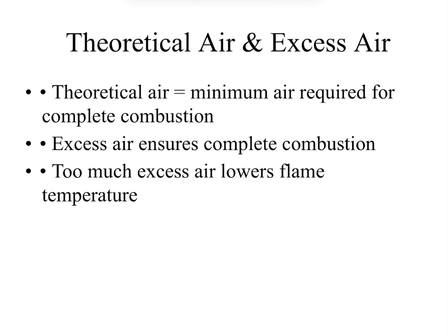And then we will move to theoretical air and excess air. Theoretical air is the minimum amount needed for complete combustion. In practice, extra air is usually supplied to ensure all fuel burns completely. However, excessive air can reduce combustion temperature. So theoretical air equals the minimum air required for complete combustion, and excess air ensures complete combustion. Too much excess air lowers flame temperature.